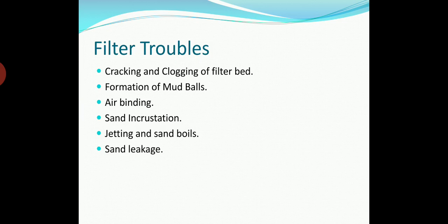Air binding. The condition of air binding is caused by the release of dissolved air and gases from water to form bubbles. These air bubbles occupy the void space of the filter media and the drainage system. Trouble is specifically likely to occur if water is saturated or supersaturated with air in solution.